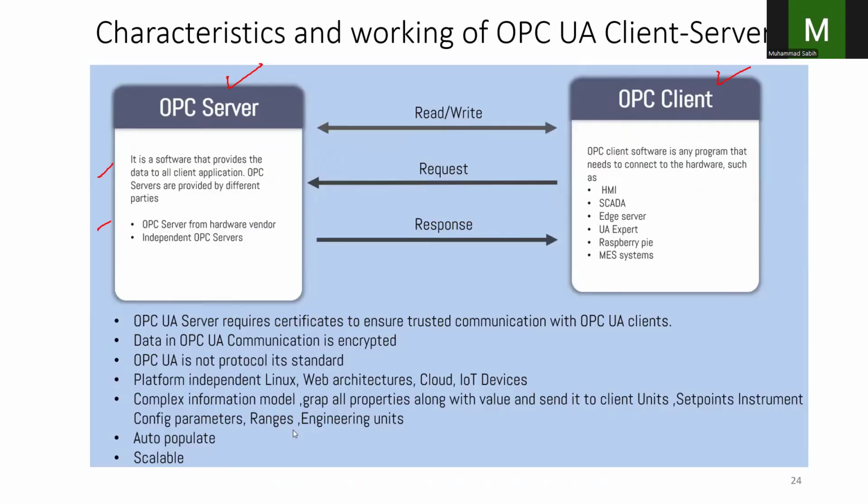And OPC clients are basically applications like the HMI, SCADA, even the Raspberry Pis, UA experts. These clients send requests to the OPC servers, and the OPC servers respond back with the necessary data. They can also read and write to the server as needed.